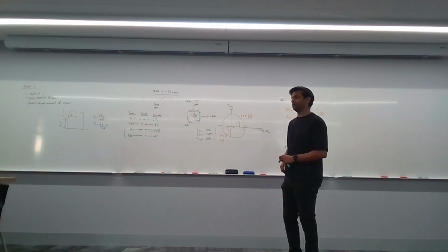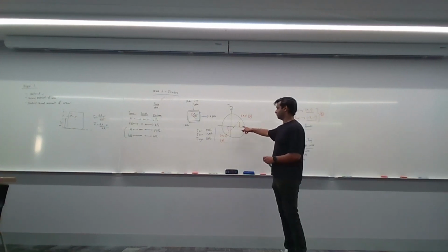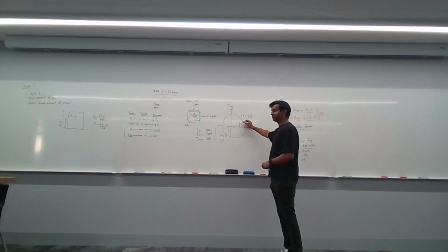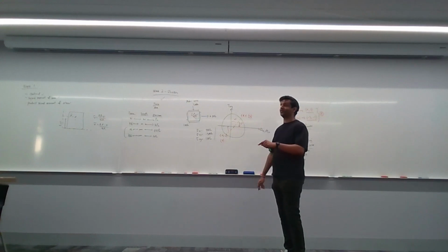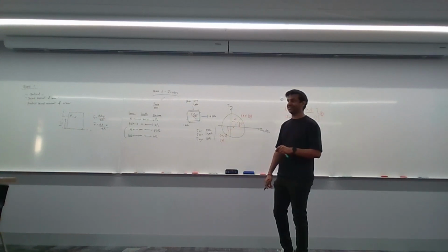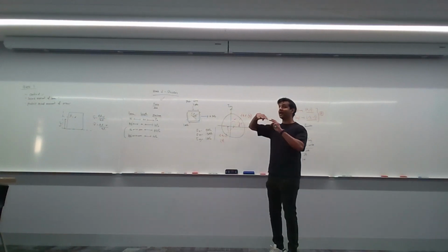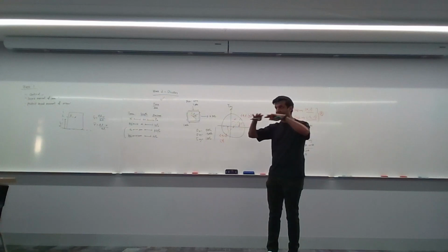So say the angle is 30, and then it goes up to 60, then it would still be going down that way. Sorry, you're saying this is 30, and then this is 60, but if the ratio was flipped instead, like this, would it still be going down this way, or would you be able to reference it to shear? Well, the question was, what's the rotation to the principal state? The principal state is the x-axis, not the y-axis. So it's basically what angle do you have to rotate by to slam it down to the x-axis?